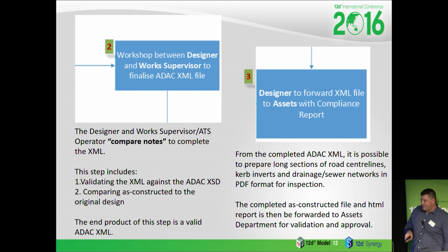Step 3 is, from the completed ADAC XML, it's possible to prepare long sections of road centrelines, if you need to, road inverts and drain and sewer networks. The completed as constructed file and HTML report is then to be forwarded to Assets Department for validation and approval.